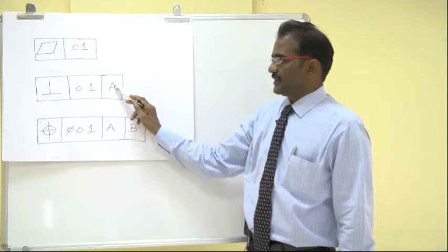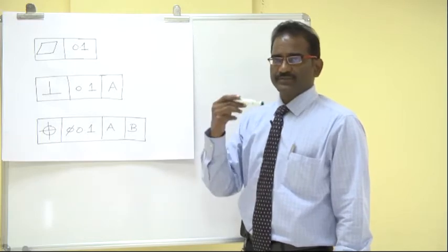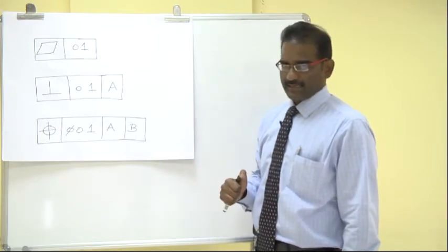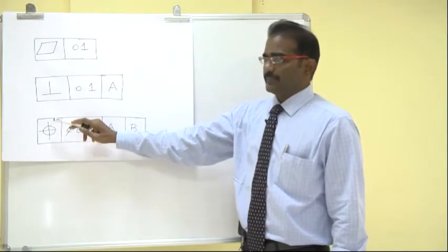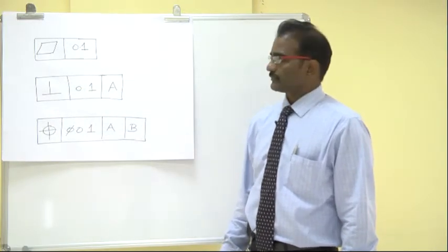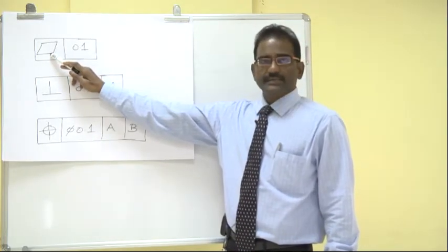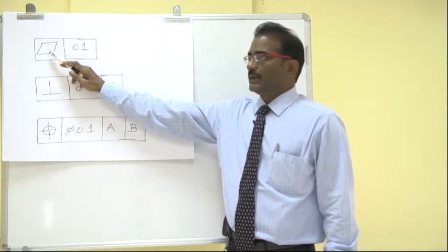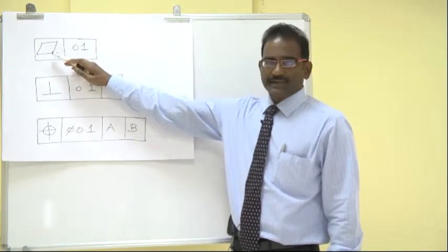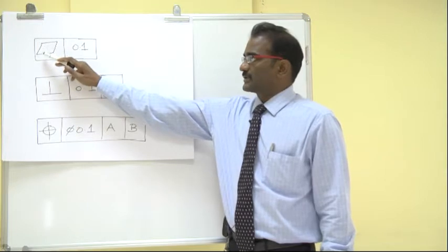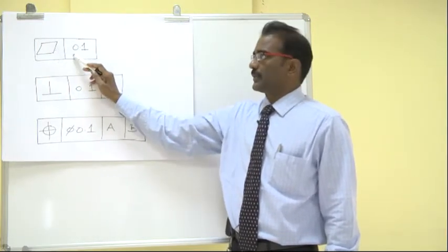or 3 or 4 or 5 compartments like shown in the earlier slide, depending upon what parameter is being controlled. By now we know flatness is a form control and datums are not applicable to the flatness parameter. That is why the flatness control will have only 2 compartments.